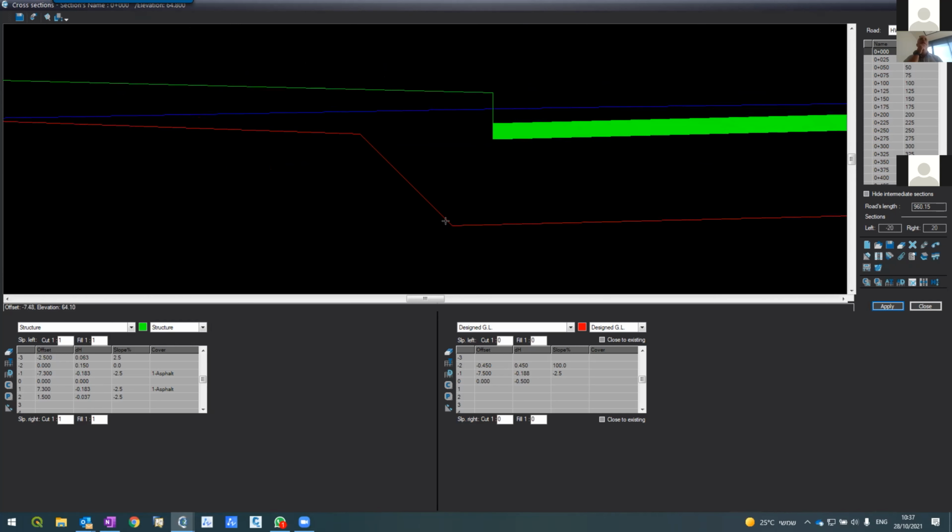Okay? Tell the software, from here, go 35 centimeter and up 35 centimeter. Why? Because I want it to be 20 cm below. Why 45? This is 0.5 minus 0.5, and this is 50 centimeter up. If I go 45, I will be at 15 cm plus 5 cm, totally 20 cm here. I hope you can follow. And from here, let me continue.